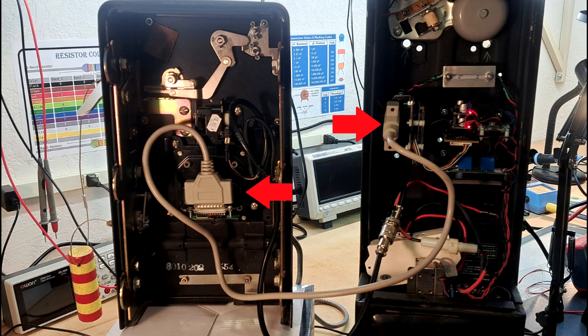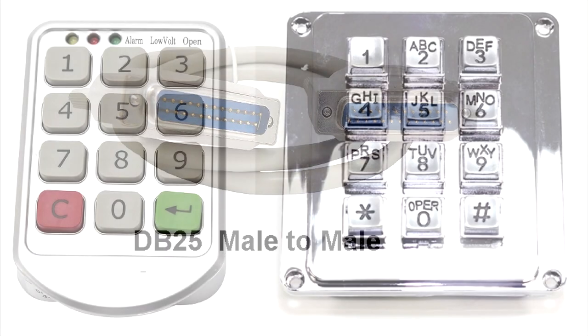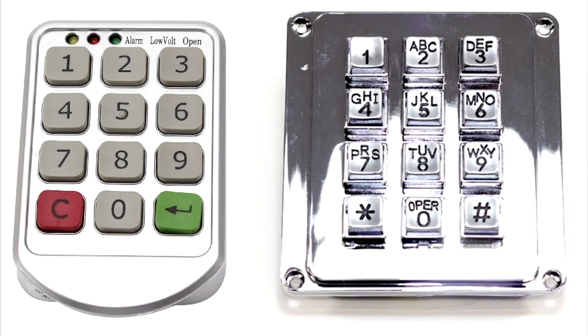Therefore, you will want to use a cable from the keypad which can be disconnected. Any parallel computer cable can be used so long as it has at least 24 or more pins. That would allow 2 pins for every 2 wires connected to each button on the keypad, including the pound and star keys. The pound key is used to activate the lock once the code is entered. The star key is to clear previous entries.